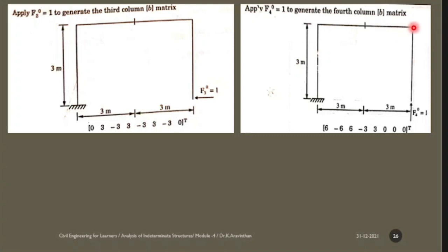And at the joint where you have load, now I am taking joint C. When you are taking joint C, what will be the moment here? So you have a force here of 1 kilonewton, this is along the axis, hence you will not be having any distance, yes or no? Load is here and it is along the axis, you are not having distance, hence you will be having 0. So 0, 0, and at this joint it will be 0. At the place where you have load, what is the moment?